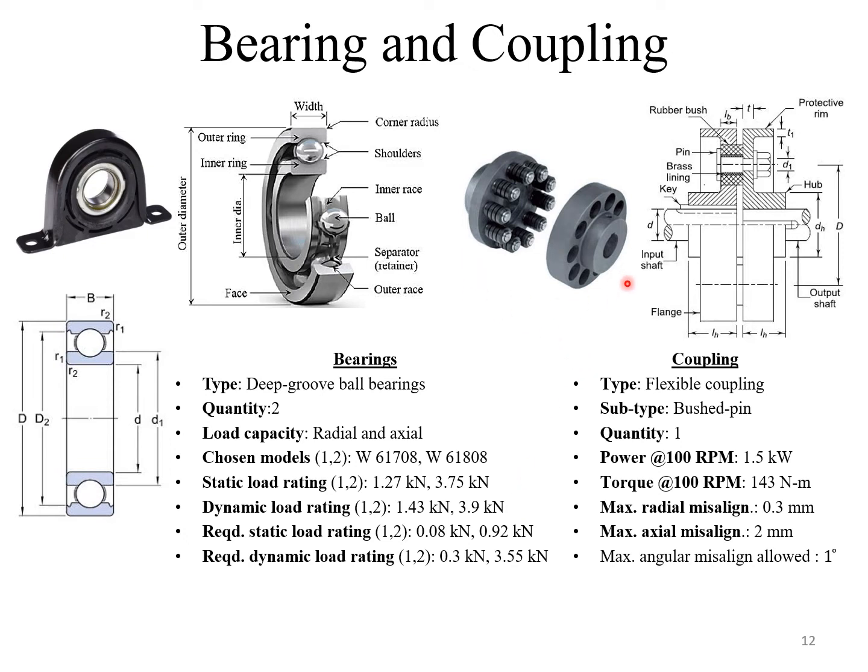A coupling is required to connect the main shaft to the gearbox. I have chosen a pin-bush flexible coupling for this purpose, as some misalignments might happen in the shafts, which the rigid coupling won't be able to compensate.